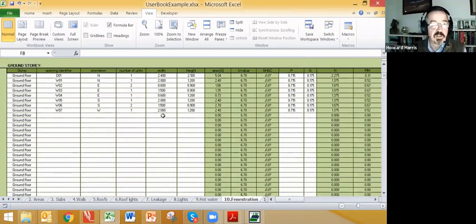In this input section you start by inserting, making use of the drop downs, your ground floor, your identifier label, in other words the orientation of the drop down, the number of such windows, the size of each of these windows. The extension of area is done automatically, as is the calculation of U value, and we'll show you how to generate the solar heat gain coefficient as well.